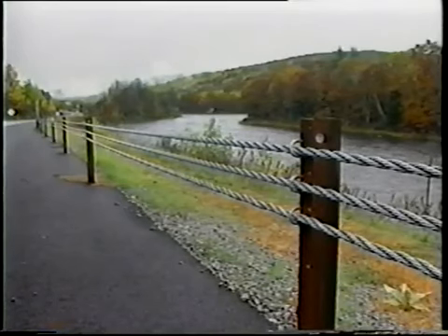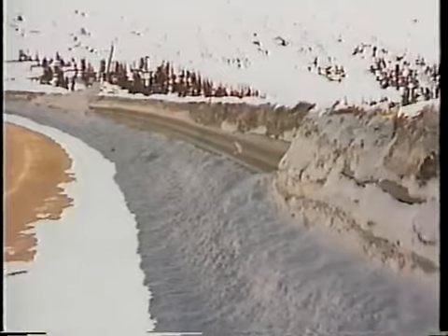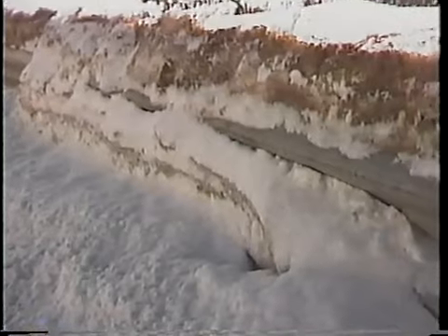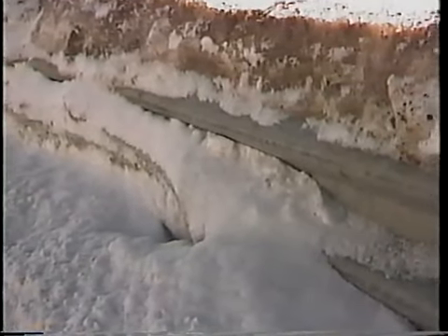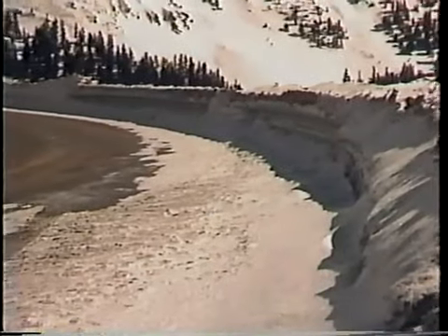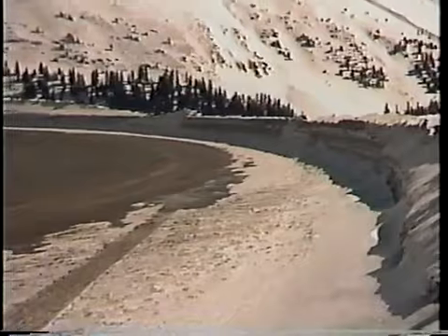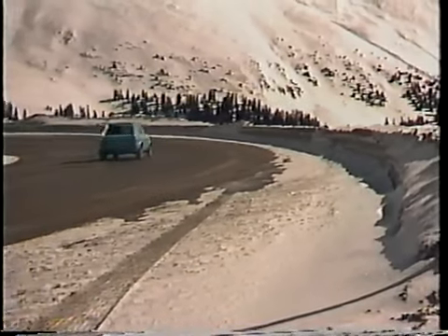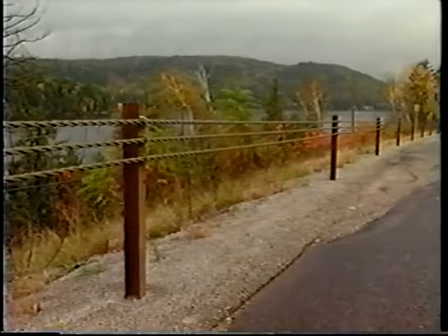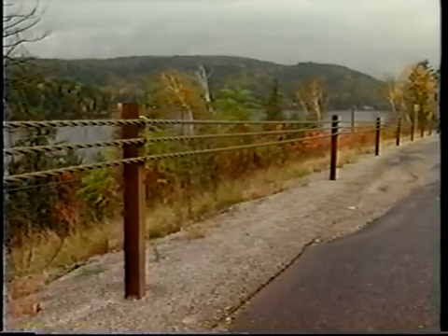Cable systems can be more aesthetically pleasing than typical W-beam or Tri-beam guardrails, since they do not obstruct the view. The slender cross-section is also an advantage in snowy regions of the country. W and Tri-beam guardrails can act like snow fences, causing a large pile of snow and ice to accumulate along the barrier. The accumulation from wind-blown snow or snow plowing can prevent the barrier from performing correctly and can also cause snow to drift onto the highway. Cable systems offer very little resistance, so most wind-blown and plowed snow will pass through the cables without accumulating.